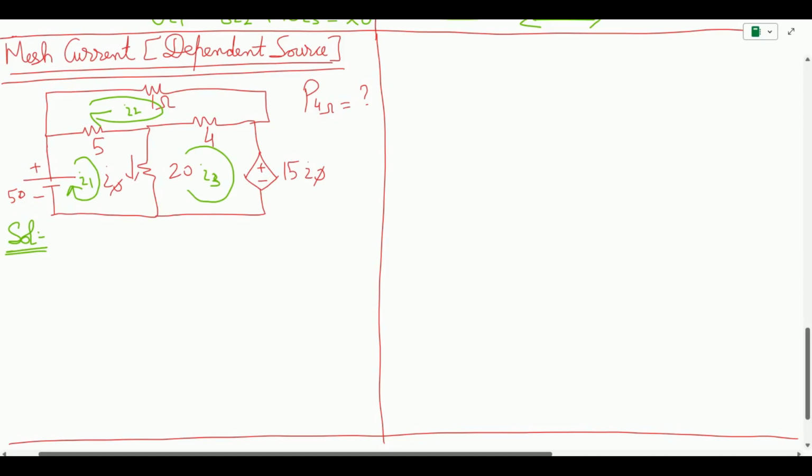Okay, we can mathematically justify as well if you want to how the circuit has equation of B minus N minus 1. The circuit has 1, 2, 3, 4, 5, 6 branches, minus node 1 is over here, second is over here, third is over here, and fourth is over here. So we have 4 minus 1, so it should have 3 meshes, and we already verified that visually and mathematically as well. Now let us apply the equation for the first mesh.